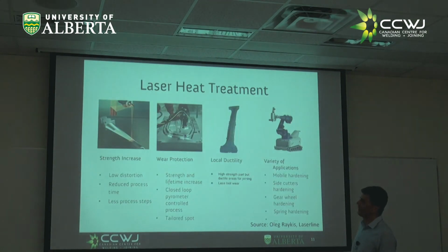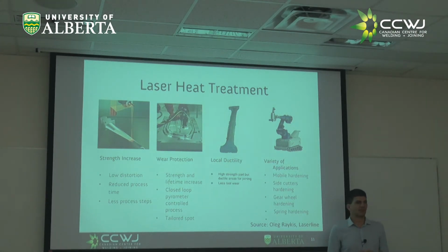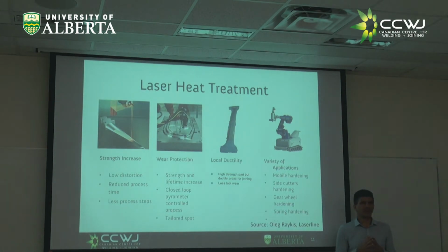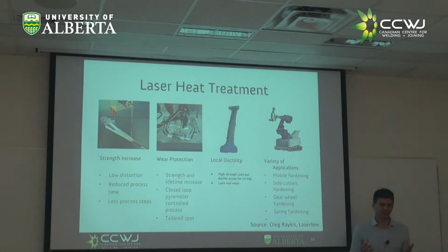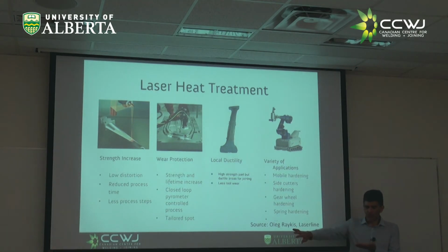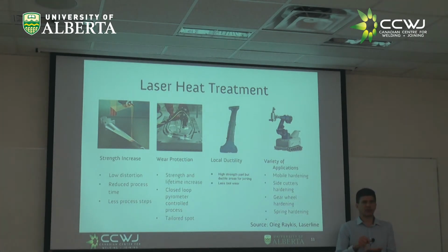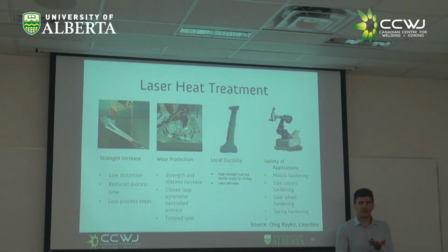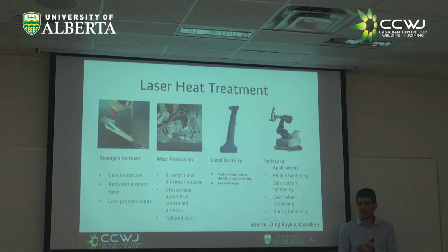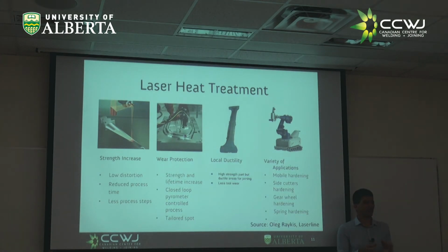Another thing you can do with lasers, and this is not welding, but it's so similar to welding I wanted to bring it up, right? Heat treatments. And this is an amazing thing because to some extent it's trivial, to some other extent it's miraculous. So with a laser, let's say you don't want to melt, but where you apply the laser gets locally hot, right? And as the laser moves, the part that was hot when the laser passed over now cools down. It's what is called self-quenching, because only the surface was hot, right? And then all this heat was absorbed by the substrate. Those of you who did heat transfer with me, this is a semi-infinite solid problem, right?